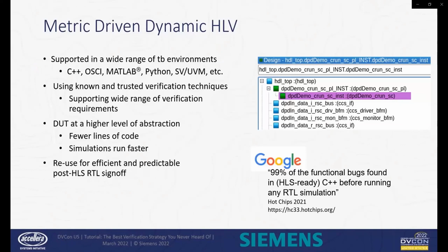While I advocate for thorough and rigorous HLV, using known and trusted verification techniques supports a wide range of verification requirements. Again, the only difference with HLV is the DUT is at a high level of abstraction. In mentioning reuse, depending upon the environment, various pieces and parts up to and including the entire test bench can be reused for efficient and predictable post-HLS RTL sign-off.